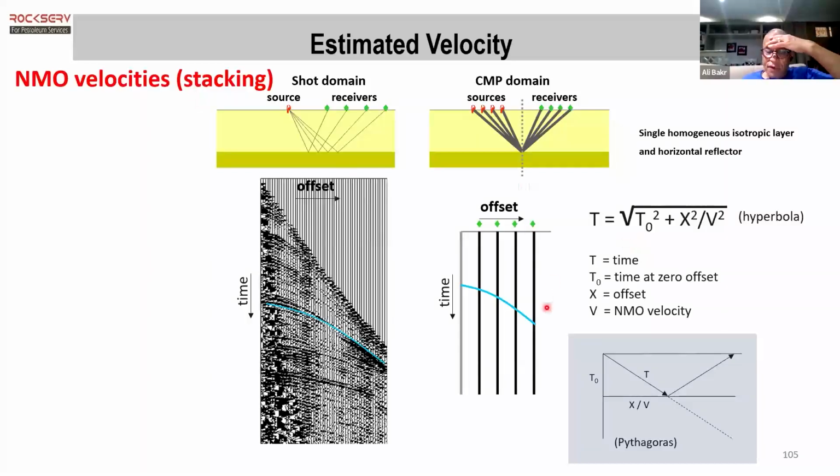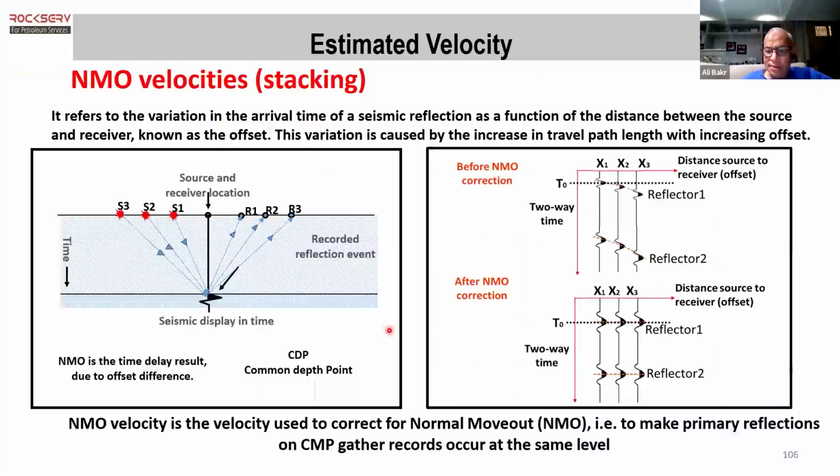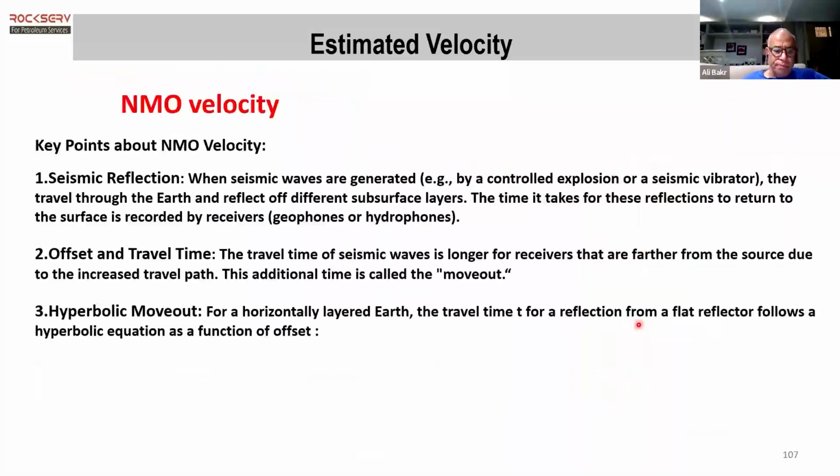This kind of velocity we do through the processing itself, using a very simple hyperbola type of work. As you can see, this reflection we can correct, and we see it on the next slide. We actually saw it even at the beginning, and we can correct this and make it look horizontal. It's not horizontal, it's just that the traces come up to each other because they are coming from the same point, and then we stack them. And this kind of velocity, we can use it.